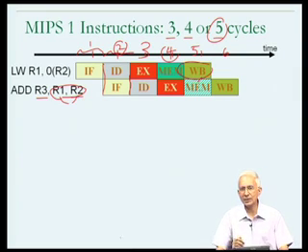So the bottom line was that the add instruction could not finish in 4 cycles because it could not do the write back in cycle number 5, since the write back hardware was currently being used by the previous instruction. So there was no benefit from trying to design the processor pipeline so that the write back of the add instruction happened in cycle number 5. The possibility was not there.